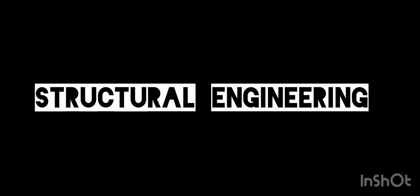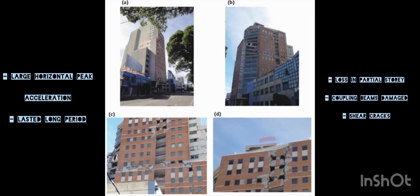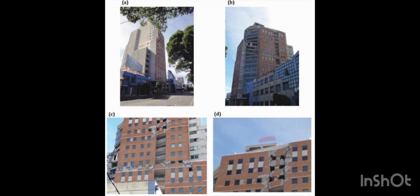Due to the magnitude of the earthquake, the horizontal peak acceleration, the X and Y planes, were large and lasted long periods, which created significant damage to buildings such as the O'Higgins Tower, as seen in the picture. The east and the south face were affected the most, and diagonal shear cracks on columns were seen on the south face. The building lost a partial story at the location of the frame setback, as seen in C, and suffered significant damage to the coupling beams, as seen in D.